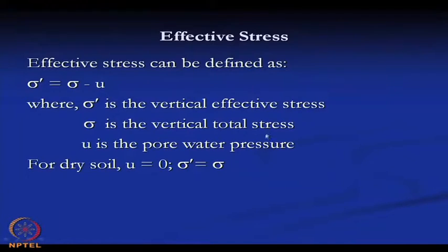Now, if we permit the water to flow, then gradually this water will flow out and the stress which was taken by the water initially will be transferred to the soil skeleton. So, as time progresses, this water goes out, and these stresses will be transferred to the soil skeleton. Now, soil will take the stress in that fashion.